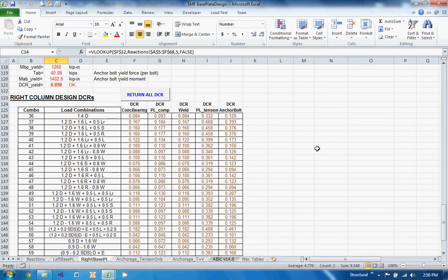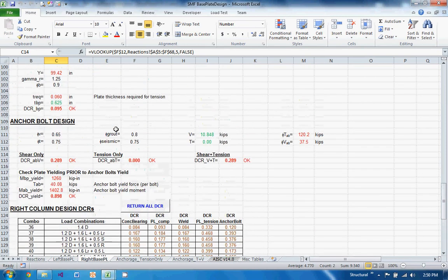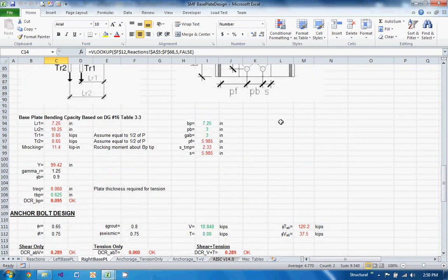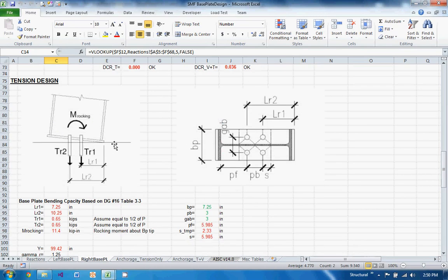For now, what you don't see here is the bearing check. That's the component I'll probably add next, to check that we are not crushing the grout too much, because when we saw testing, the first mode is probably grout crushing.